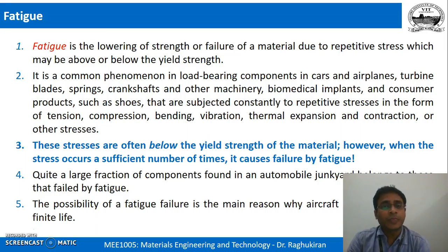How come? Because you are applying it repeatedly again and again. It's what we call cyclic load. So even though you haven't applied the load beyond its yield strength, the material still fails under repetitive stress conditions. This is what we call fatigue failure.